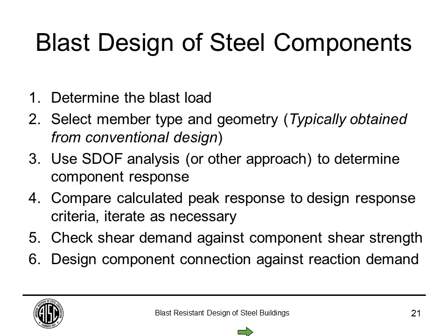And when we look at a component, we concentrate on the dominant mode of response. As I mentioned before, typically we want to make sure that components are designed in the flexural mode of response because it allows the components to bend and absorb a lot of energy, which results in efficient components that are not very expensive. If we were trying to design against blast loads, keeping components in the elastic range, it would be just too expensive. So the first step is to determine your blast load. We're going to talk about that and how we do that.